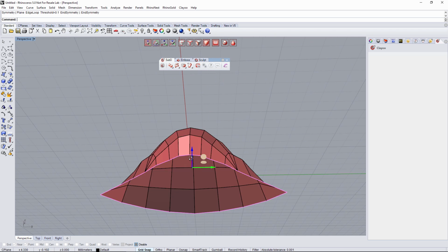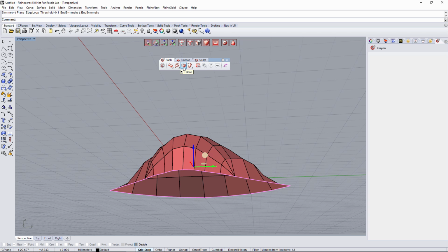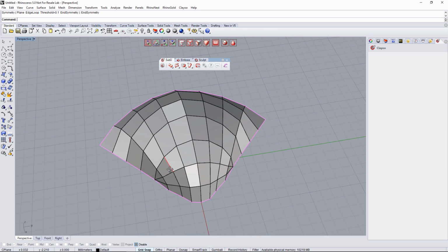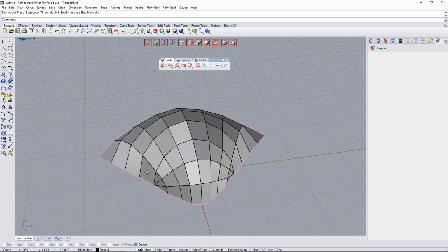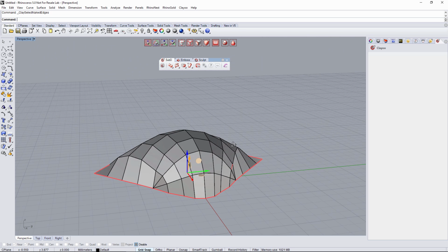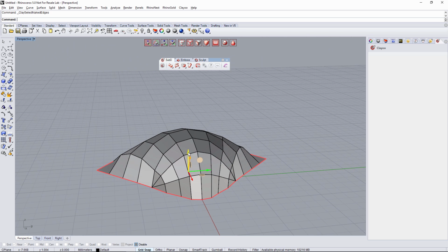So what I'm going to do is grab it, go to the Addition tab, and give it a thickness. Okay, first of all, before giving the thickness, I'm going to create a small extrusion down here. So I'm going to select the entire loop, so select the naked edges on the scene. I'm going to hold Alt on my keyboard, and create a small extrusion like this.